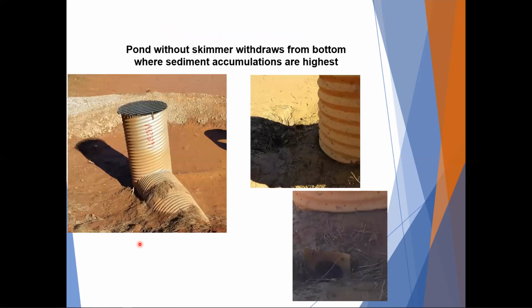So typically before now, you've probably seen most of your basins had a riser with an orifice probably at the bottom of the riser, and it pulls in a lot of mud from the bottom of the pond. Probably have a check dam in front of it. The back side of this looks okay, but you can see how muddy this pond is. The front side is probably pretty much closed off or blinded off, but it is filtering some of the water that comes through there.